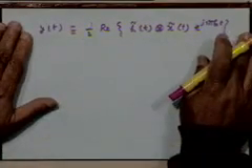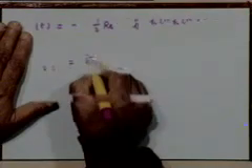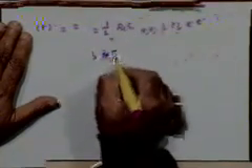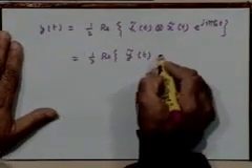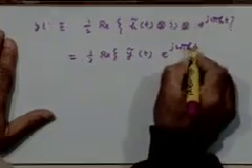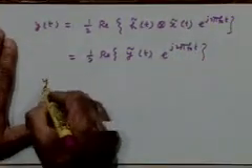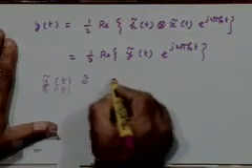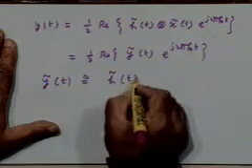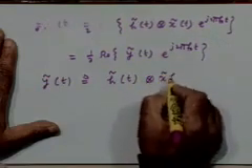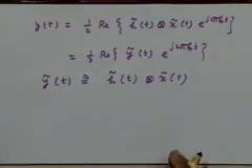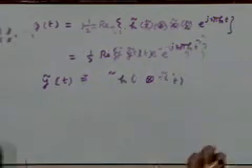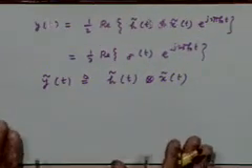So now let's look at this. This is the final result we got. Can I write it like this? Half of real part of, say, y tilde t e to the power j2 pi f naught t, where I define y tilde t to be the convolution of h tilde t with x tilde t, right? And this is a result which has a lesson for us, the most important lesson which I want to talk about in this discussion.